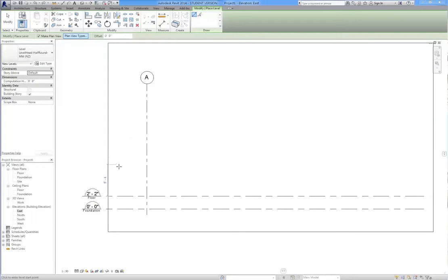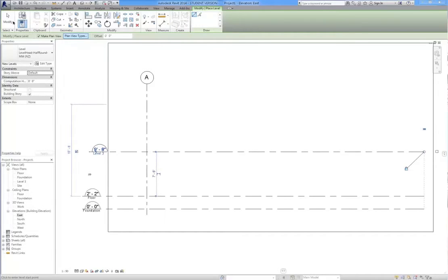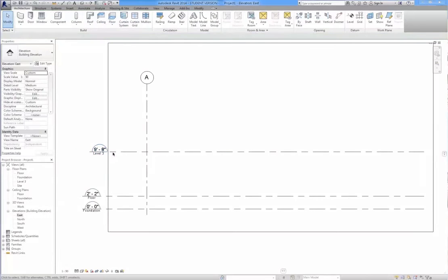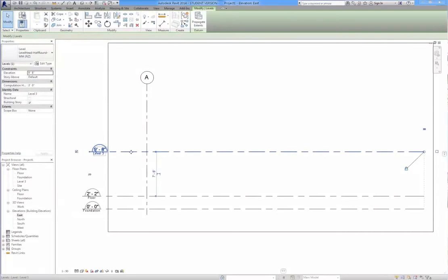And then I'll click above it and drag along, and if I drag along far enough it snaps to where the other guys are, and that'll line up nicely and make it look nice. So I'll just go yep, there, and that's all good. So it's called level 3, and it made a new floor plan called level 3. And then if I click modify again, and click on that level again, you can drag out.